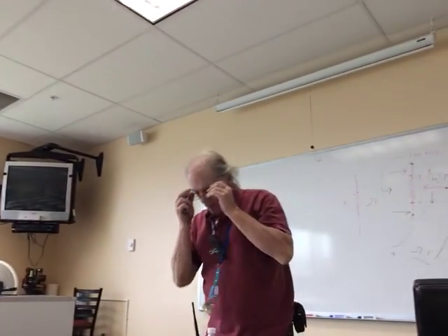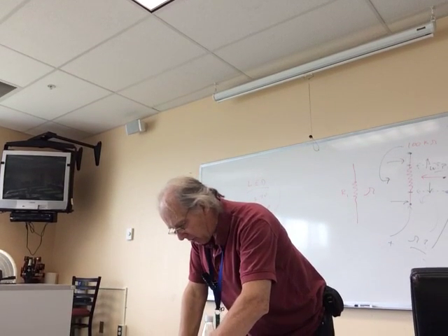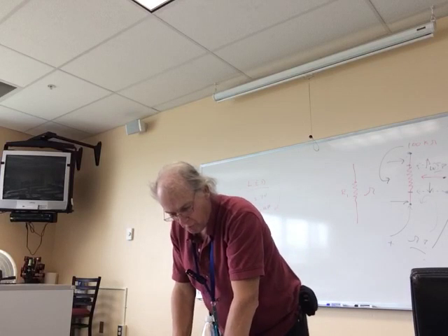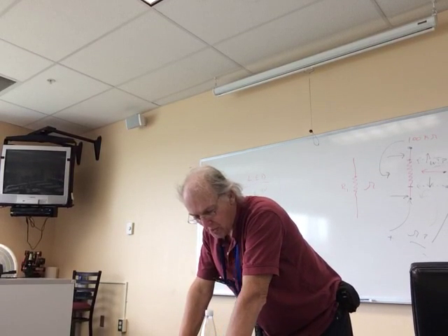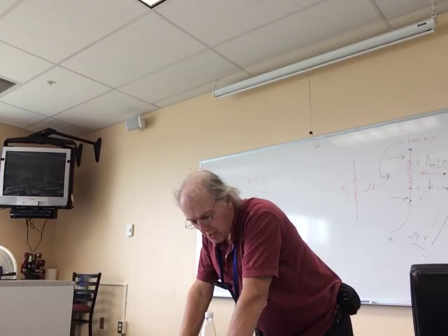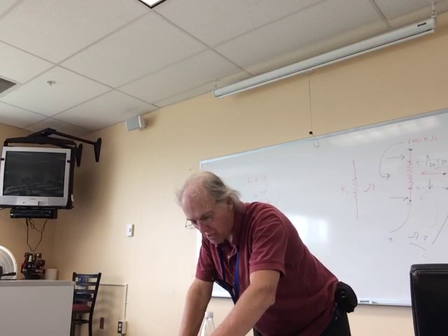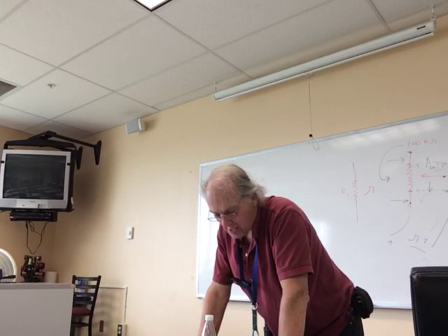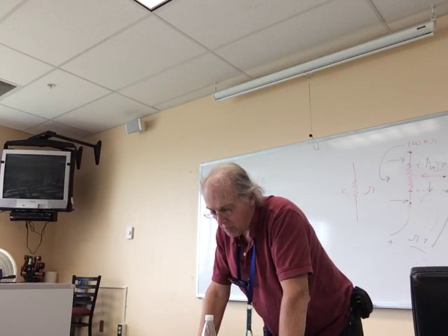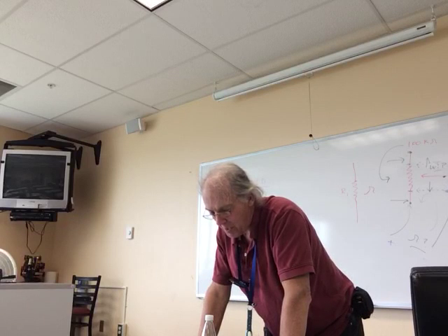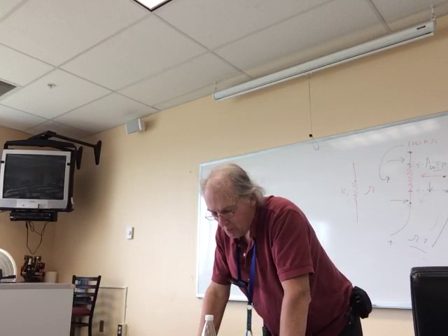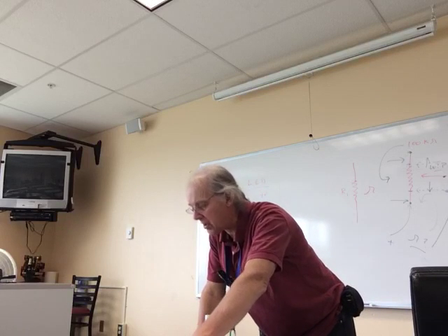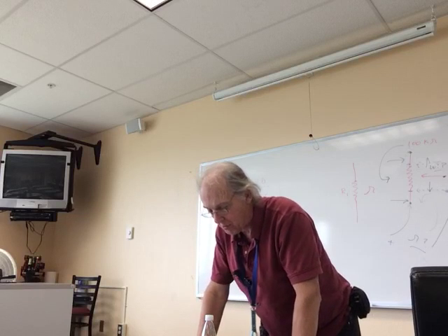Now, if you go on to the next page, you will see voltage dividers 8-16. Well, 8-15 has 3 resistors, and then notice that they have a resistor off to the side on the bottom. Again, that's a small resistance. Let's see, it's 1K and 10K. So that 10K will affect that 1K, and it'll look parallel. The 1 milliamp will want to split between the two. It's not a bias circuit, it's actually a load circuit. So you have to take that into account.